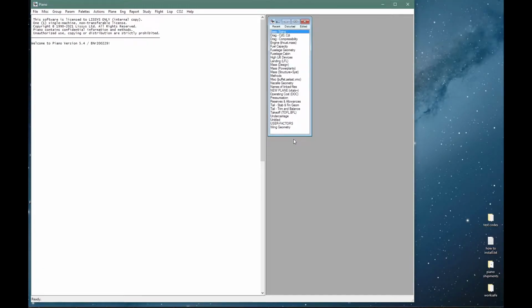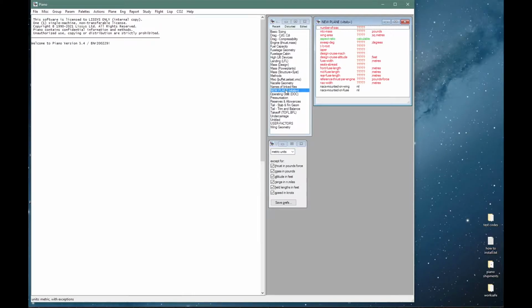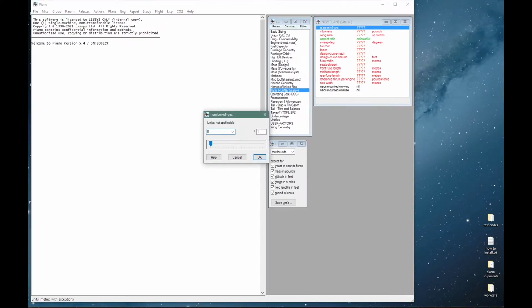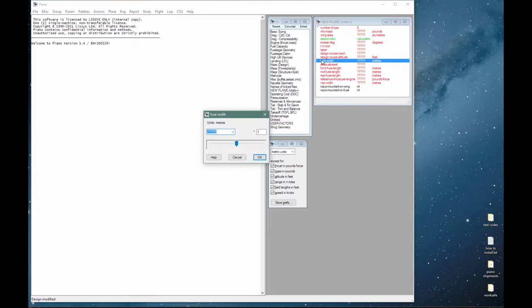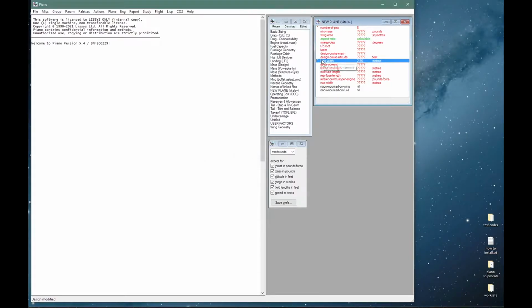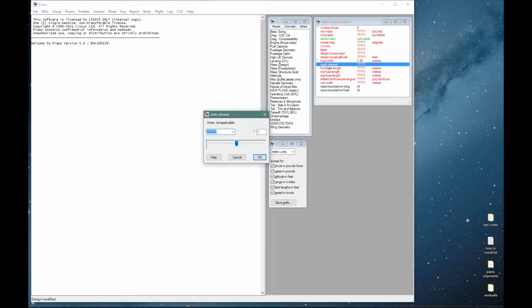We will launch straight into our definition. Set masses to imperial, new plane palette, 8 passengers in something like an NBAA club seating setup. I estimate external fuselage width at around 2.96 meters, broadly compatible with the quoted internal cabin width of 2.77. Seats abreast is 2.